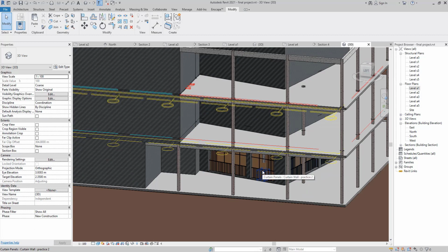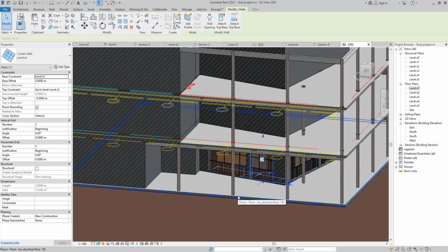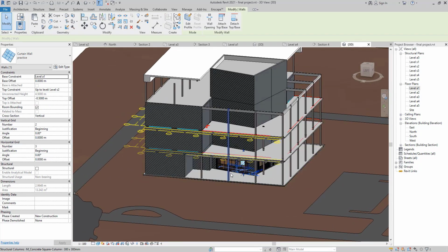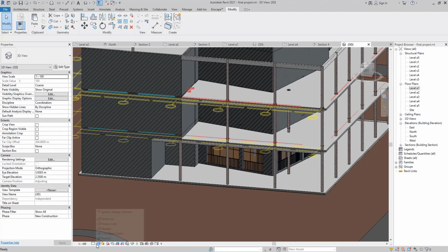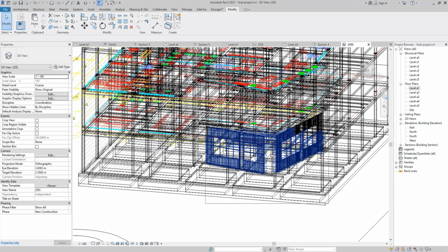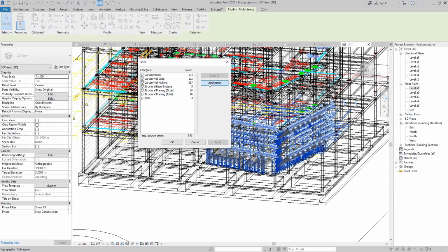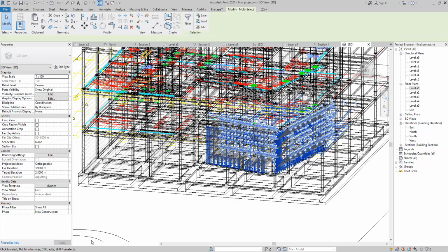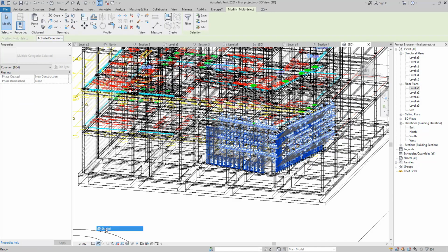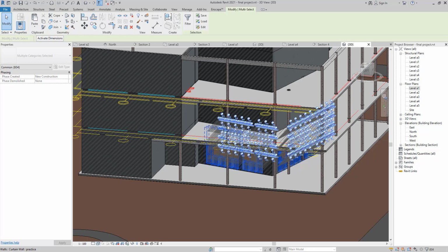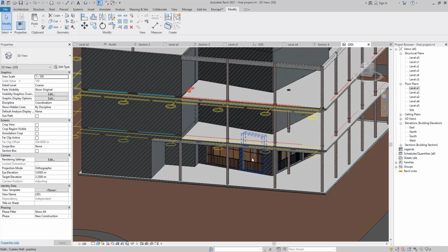So we are just going to click our panel. For example, right now we have different options. We can click one by one, but instead of wasting our time, we go to the wireframe mode. We will go to here, filter, check none. We can pick up our curtain wall from here, curtain wall, and here we go. For example, it was one of the other methods. Why not?